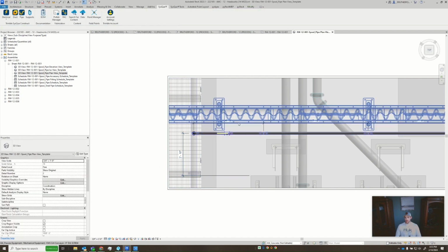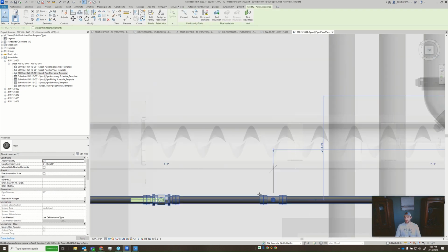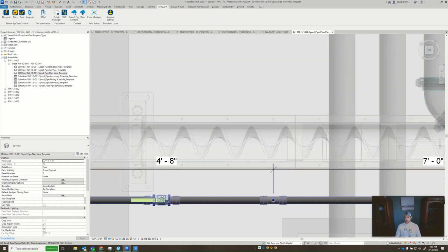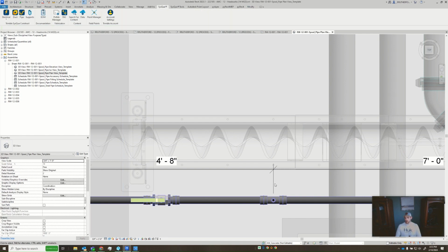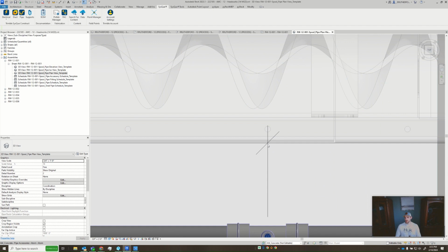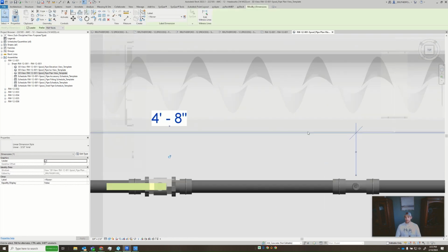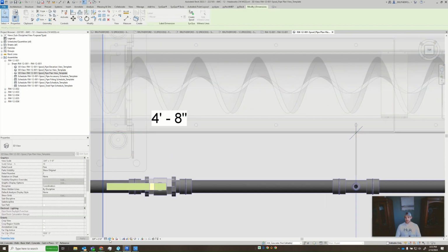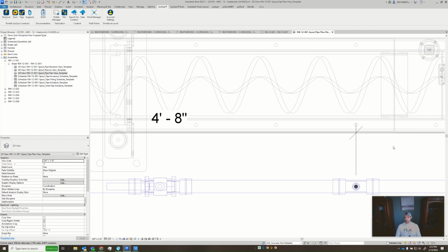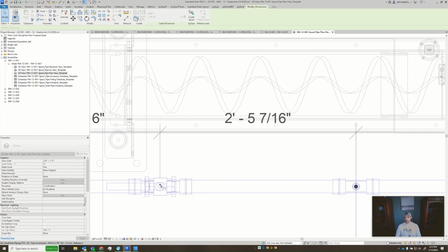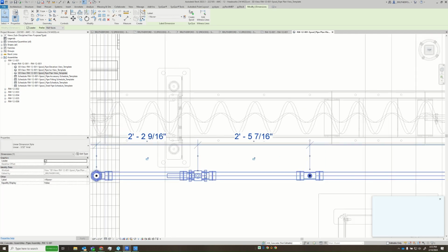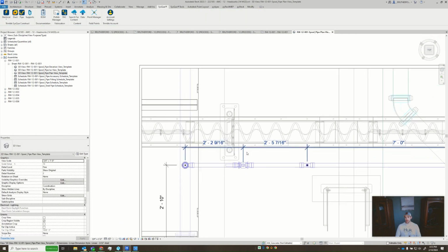A lot of times you may have to go back in, and if you forgot to do an element, I purposely left this one out, but for instance, I don't have the center line on this particular element. I will go in to this dimension tool here, sometimes it's hard to grab, go back to edit witness lines, and because there's not really an easy way to select that center, I'll go to wireframe. Sometimes it won't work, sometimes it will. When you're dealing with circles, you can get points like that. So there it goes, it adds one, and I'm happy with that.